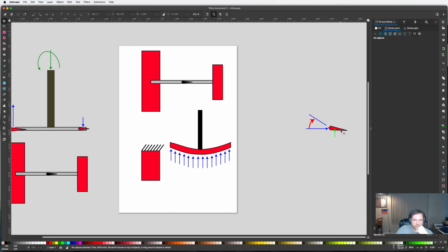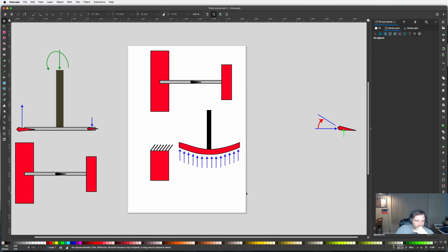This is some angle that this wing is hitting or approaching the water. So that coefficient of 2 pi times angle of attack, that's assuming effectively an infinite wing. It's a very simple approximation, because it's ignoring anything that happens at the edge of the wing here. That's a big problem. Eventually, we're going to have to deal with that, but in reality, the water is going to be doing something different on this side.